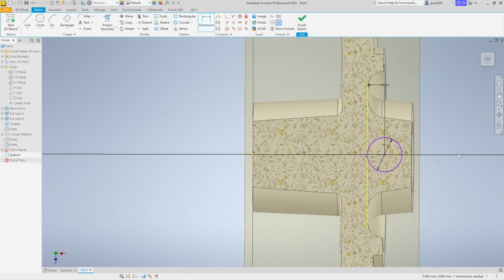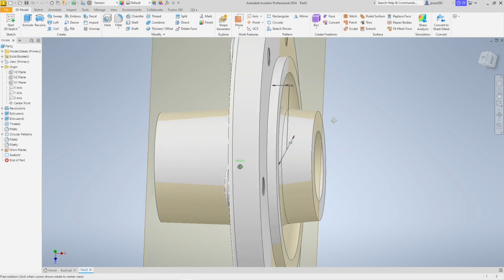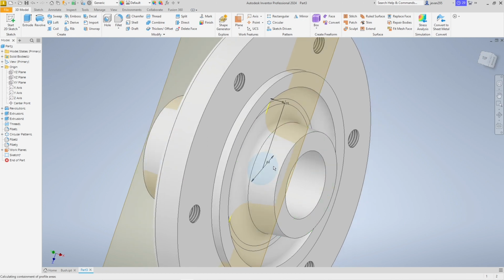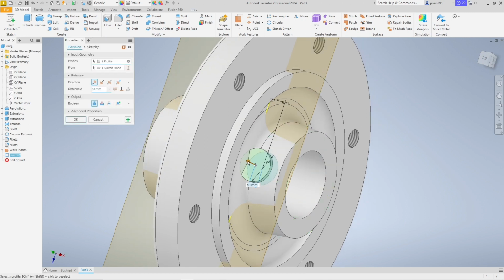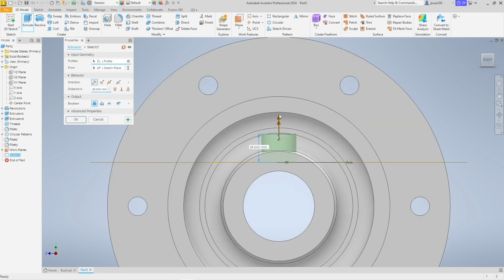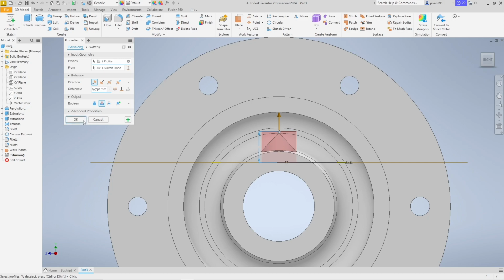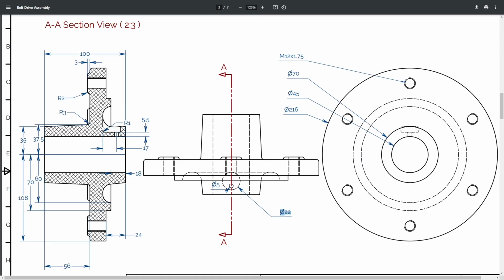Now, this is pretty cool, but we want to extrude this, and we want to extrude it up. We're going to finish sketch. Now, once we finish sketch, we're going to extrude. We're going to extrude up until, and if we look from our, in this case, right, and if we rotate it so it looks upright, we then want to drag it up until it is perfectly in the middle there. It's not below this circle, and it's not above this circle. We then want to press cut. This means we have now created this hole here, this down, across, and back up again.